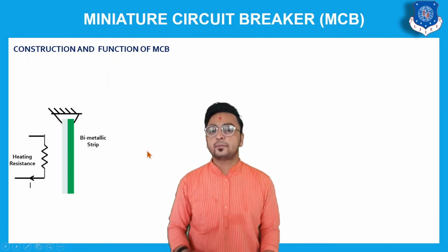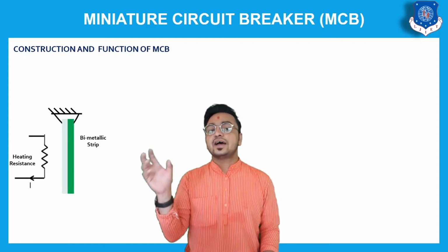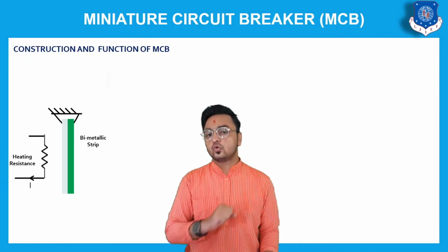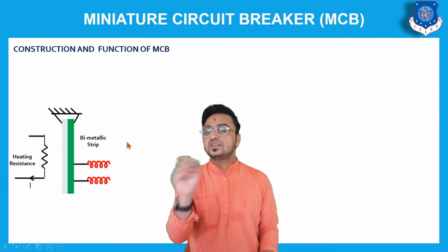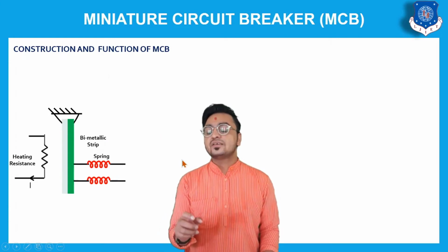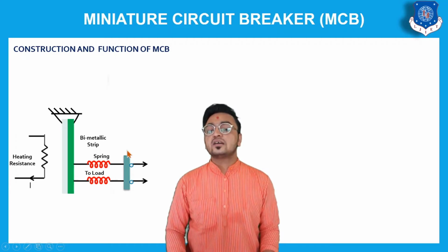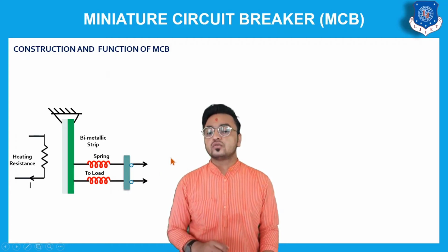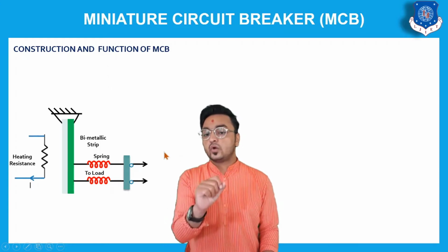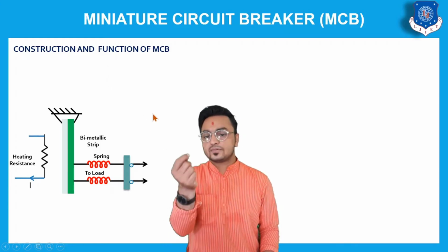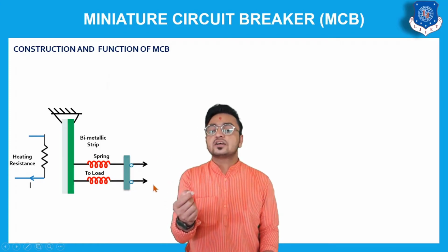That is the high temperature. So basically, we are using the concept of that high temperature to turn off the circuit over here. And for that, we arrange a bimetallic strip over here, and with that bimetallic strip, a mechanism is connected over here. Here we have connected a contact of a live wire. So basically these contacts are connected with a live circuit. Means here one connection will be connected over here, and the other connection is connected over here.